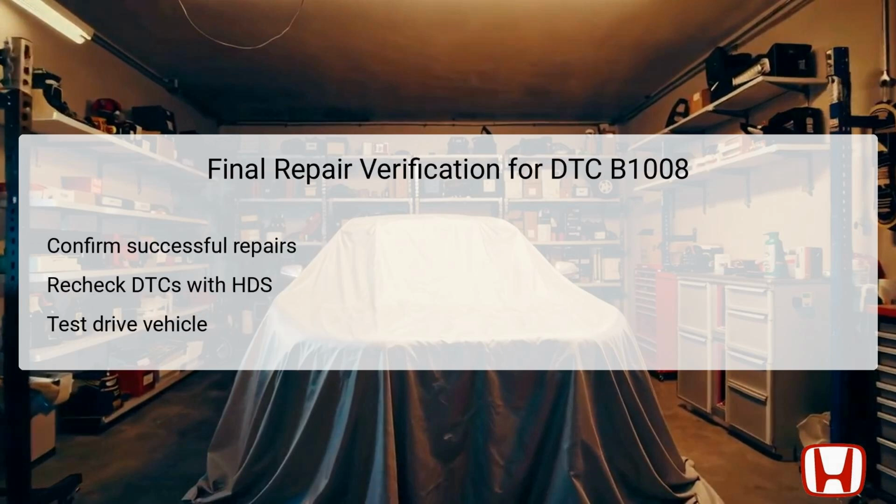Final repair verification is a critical phase in the troubleshooting process for DTC B1008. After making any necessary repairs or replacements, it's crucial to confirm that the work was successful. This can be achieved by rechecking the DTCs using the HDS tool to ensure that no related codes are present.